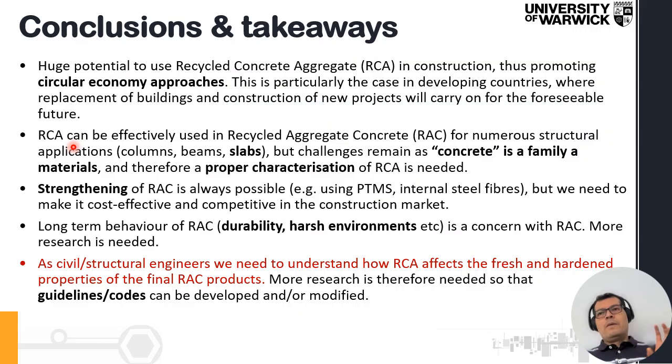Now, we can actually use the recycled concrete aggregates in recycled aggregate concrete. That's the new concrete we're producing for different structural applications. The ones we are examining at the moment are columns, beams. I didn't show you much on beams, but we also did beams, and particularly slabs. I think slabs, we basically can use them as they are now.